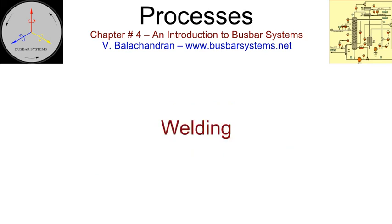Welding. Welding is the most efficient and preferred form of jointing of copper or aluminium conductors. It is permanent, does not deteriorate with time, requires no maintenance, and is extremely economical. However, welding of copper or aluminium needs expertise and specific infrastructure. Repetitive welding at works can be undertaken by robots. Welding at the site is mostly manual and requires skilled operators.